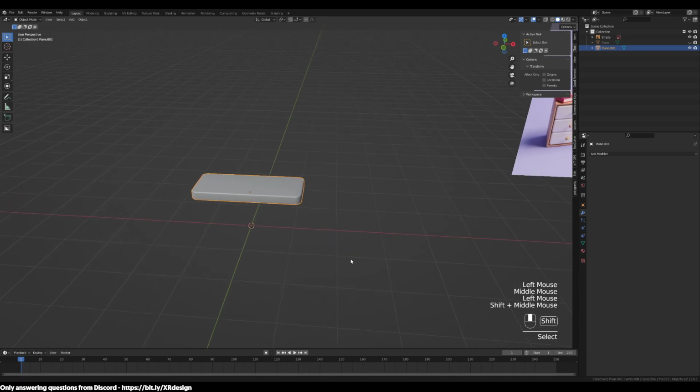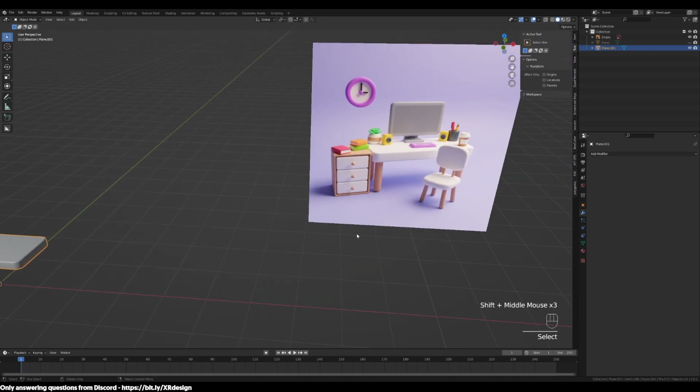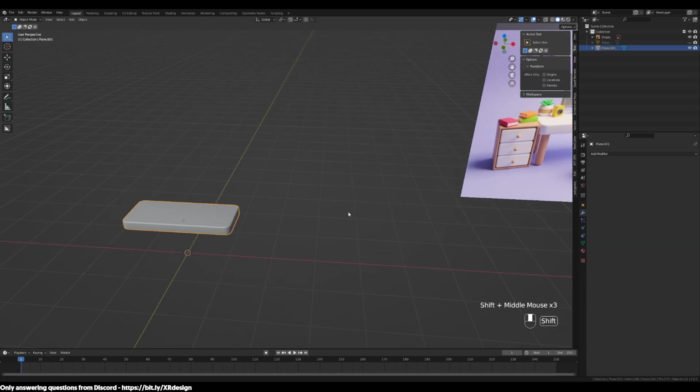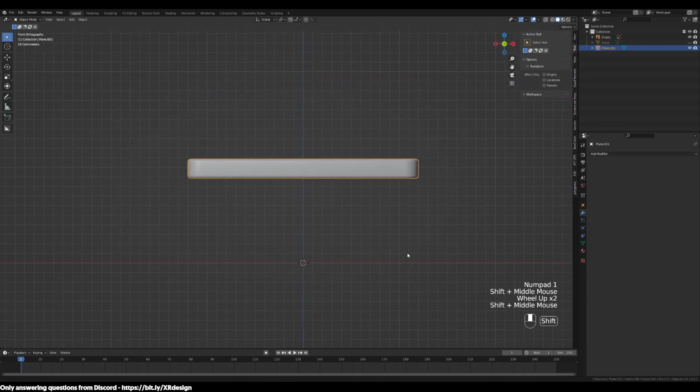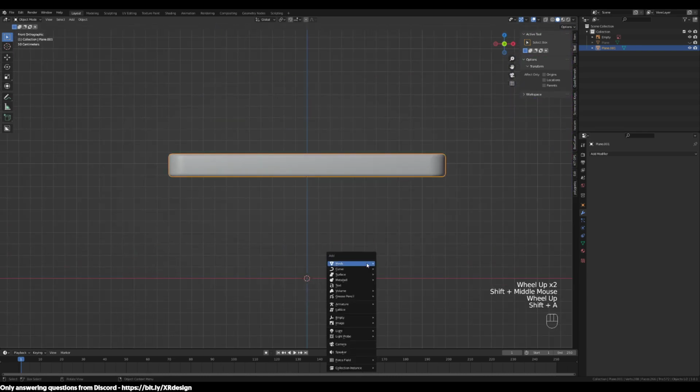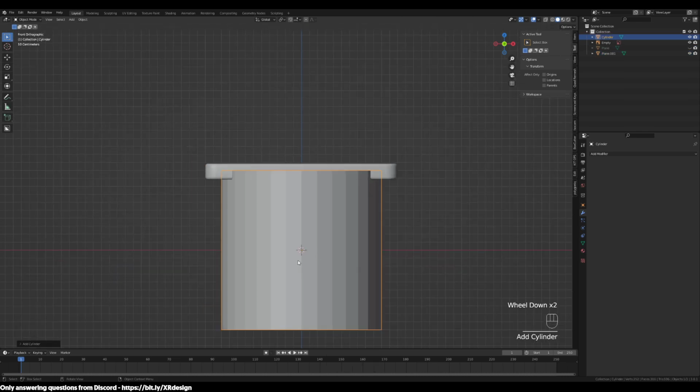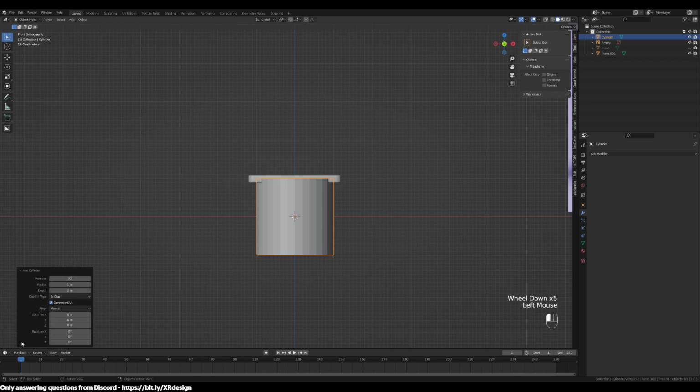We're gonna create the legs, and we're gonna use the mirror modifier that we touched upon last week. But let's start with creating that one leg first. I'm gonna go to front view, numpad 1, Shift A to add a cylinder, and I'm just gonna change the vertices value here to, let's say 12.